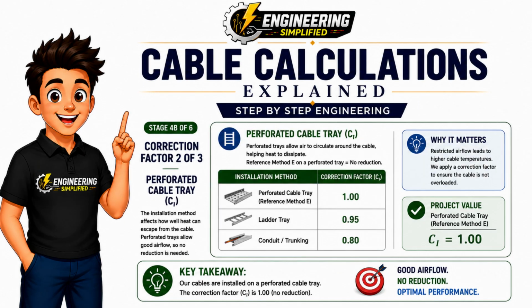Next, we consider the installation method. Our cable is installed on a perforated cable tray using reference method E. A perforated tray allows air to circulate freely around the cable, helping heat escape efficiently. Because cooling is good, no reduction in current carrying capacity is required. Therefore, the installation correction factor is 1.00, meaning the published cable rating remains unchanged.